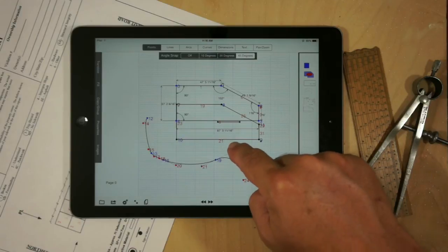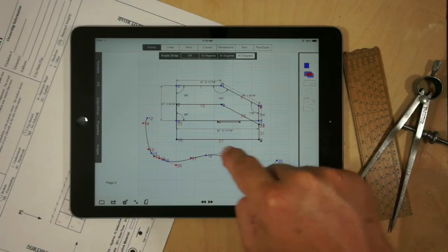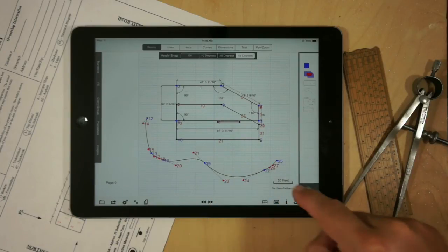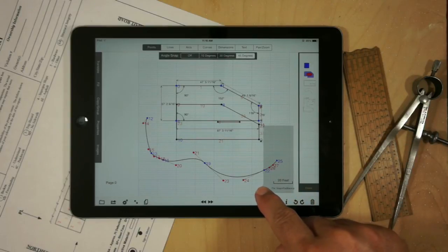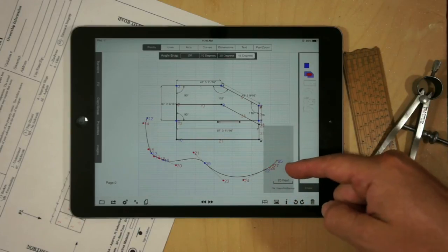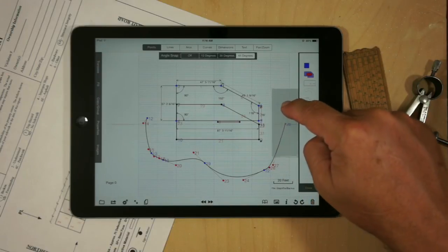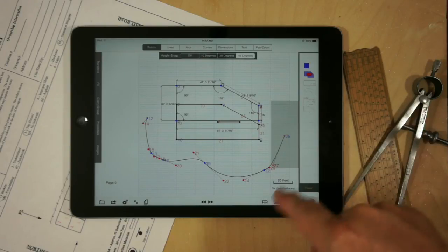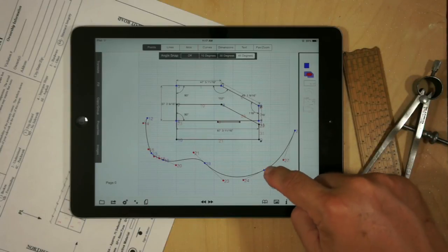Now, we can manipulate the geometry of the Bezier curve. We can grab the center and move it down. It will move both of the control points, etc. Or we can use the selection area, and we can grab the points that we are interested in moving. And say, for example, we just want this endpoint, turn everything off, select the endpoint, and then drag the endpoint. Turn everything off, grab the control point and the endpoint, and move both of those 2 points, etc.